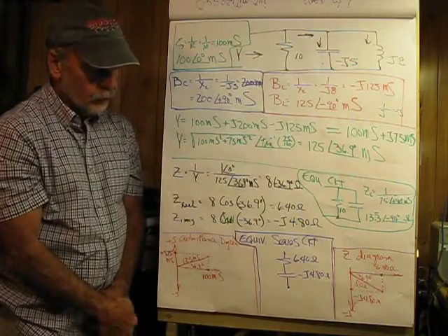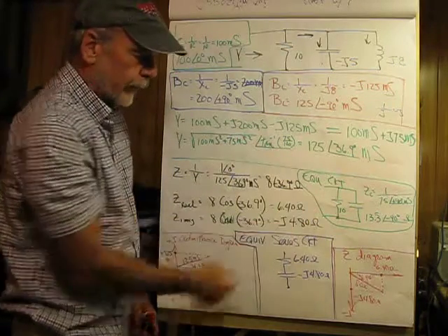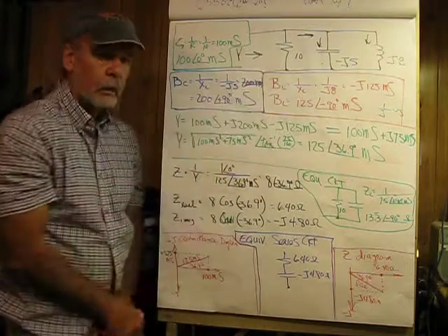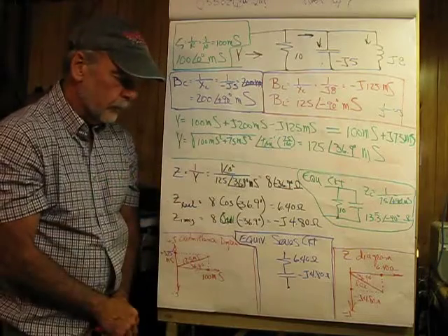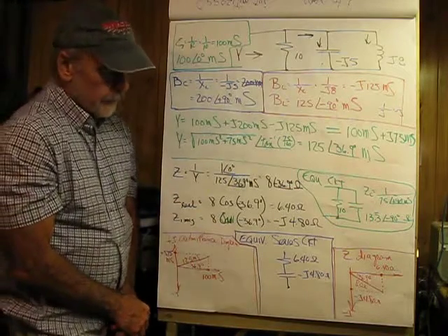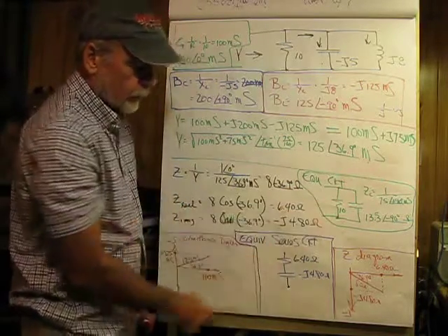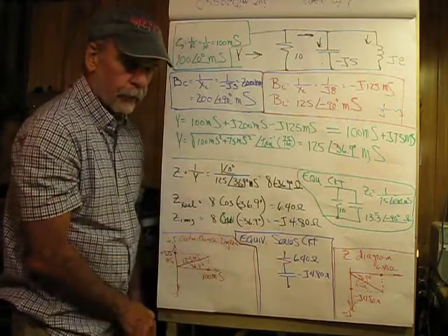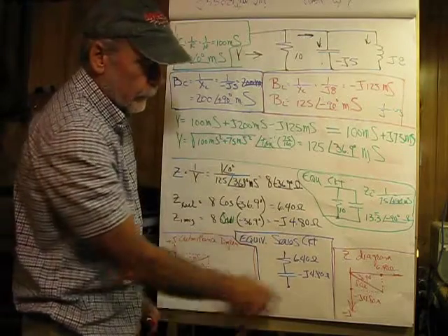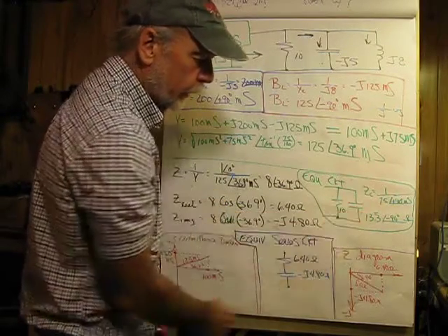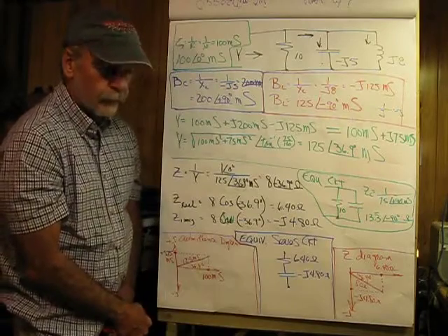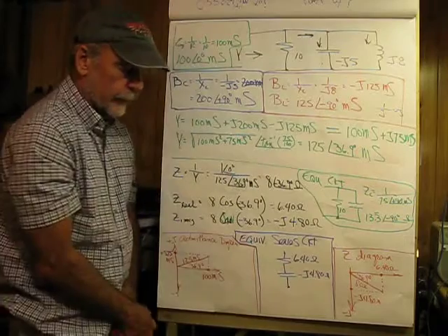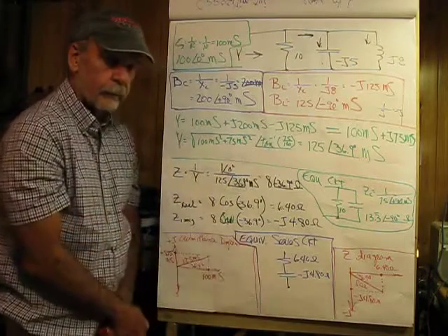And what we're seeing here is a component of that in our little parallel circuit. And that would be a parallel resonant circuit, but we're not there yet. So notice that these values are very much different. The 10 ohms parallel is equivalent to 6.4 ohms series, and the 13.3 ohms parallel for the capacitor is equal to negative J 4.8 ohms for the series circuit.